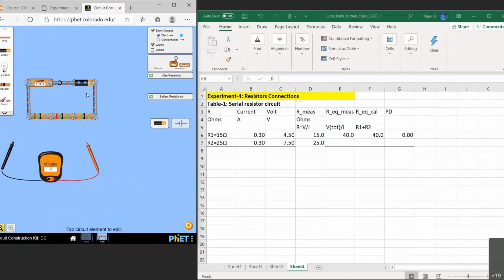Now you can see the circuit is connected. Usually, if you're doing this in class, there are certain precautions we have to take, right? Before you do anything to the circuit, we have to switch off first, disconnect the voltage and battery, then disconnect this point and add the new resistance, then switch on and measure all the numbers, right?